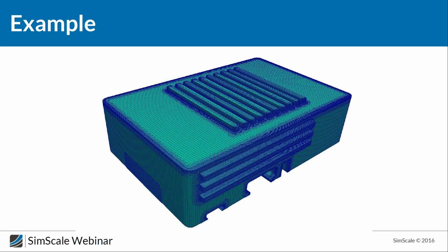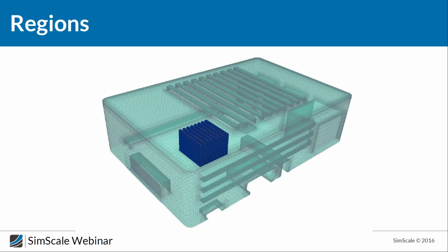It's not too important to understand exactly what is happening here, but basically what we see so far is the fluid domain from the outside. So let's look through the domain now. As you see, we see the heat sink very distinctly in the middle of the fluid domain. The type of this heat sink is going to be solid, and it is located inside the fluid.